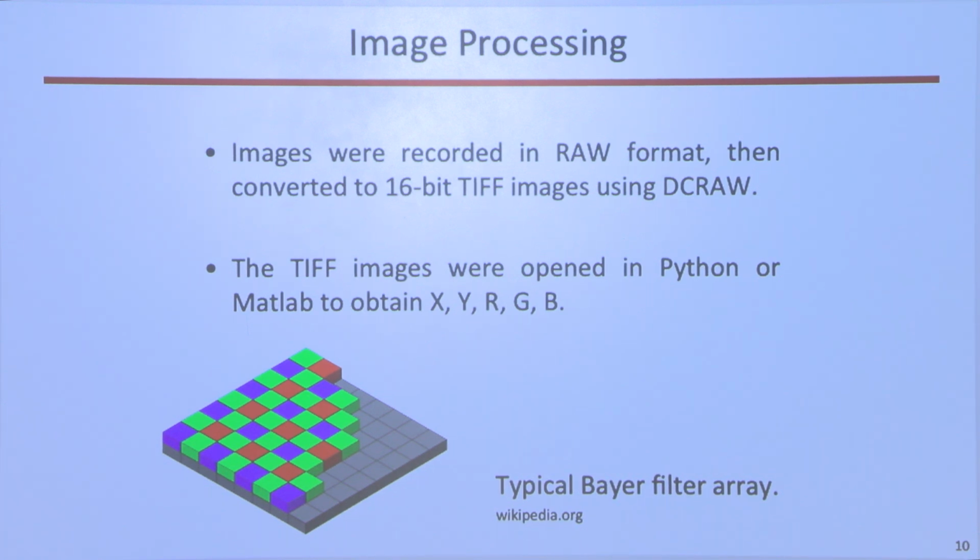And we haven't really worried about that because what Sony does is that at every location, whether it's a green or red or blue pixel, they'll give you the pixel value for all three. And it does some fancy interpolation. It says, okay, if I've got a red cell here and here and here, it interpolates to estimate the red pixel value in the center.